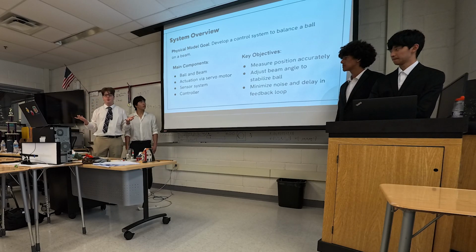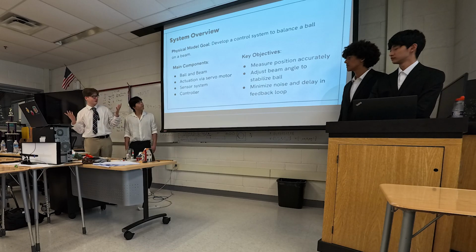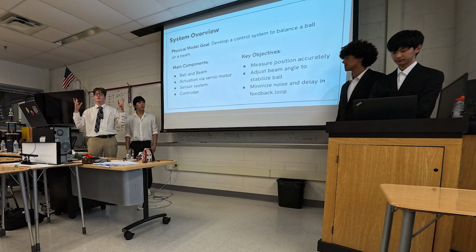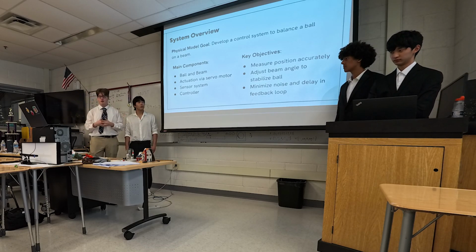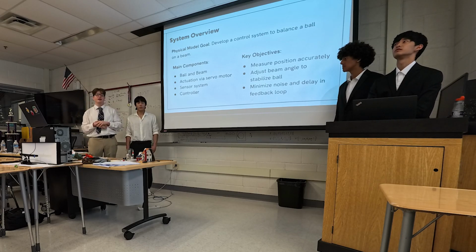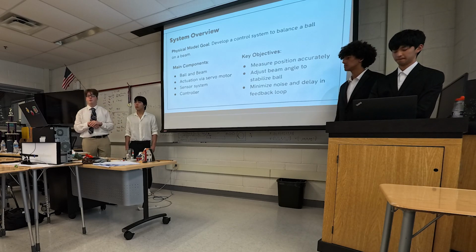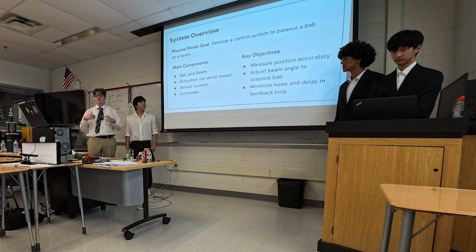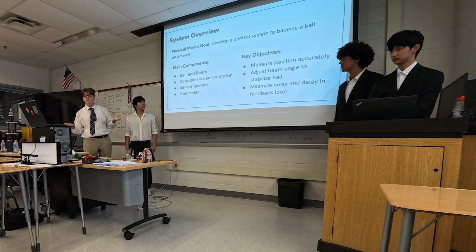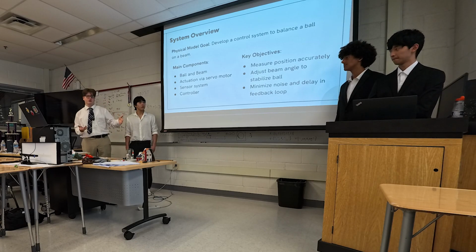The main components, of course, are the actual ball and beam; the servo, which is the way that the AI is going to control the physical model, by setting the angle of the beam; the sensor system, which initially was an ultrasonic sensor and then we switched to computer vision, and we'll talk more about that in a later slide; and the controller, which in this case is the actual artificial intelligence, or in our case, since we didn't get to that, the PID controller, which Leo described before.